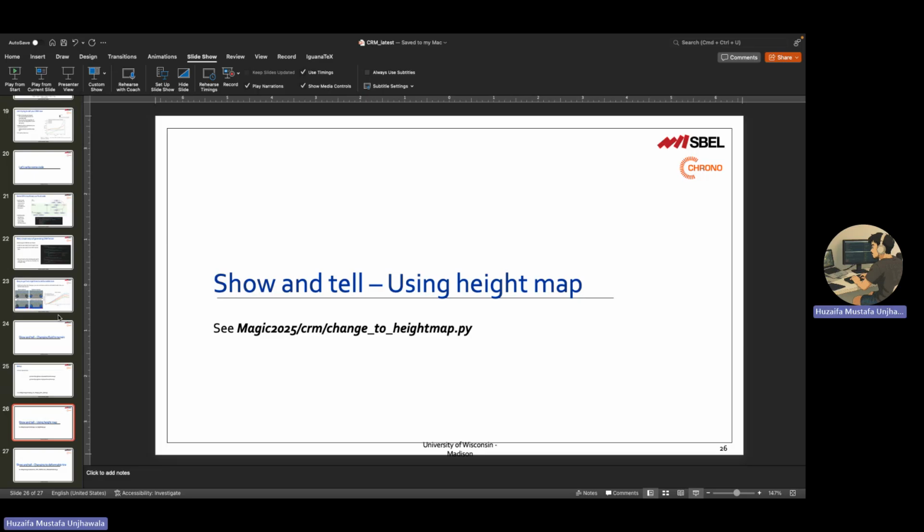Nice. Okay. That'd be interesting. Yeah, because with variable resolution, for example, in this case, if my tire had very thin grousers or some features that I want to capture, I need my markers to be the same spacing as my terrain. So to capture these grousers, if I go to a very fine resolution, my entire terrain has to be a fine resolution. My computational cost goes crazy. So yeah, I'll be very interested in doing the variable resolution stuff.